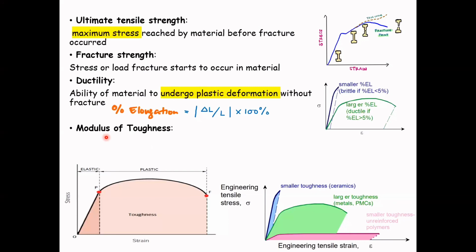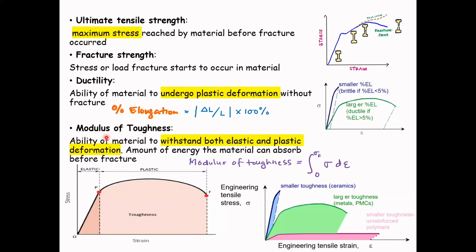It is defined as the amount of strain energy density, or the strain energy per unit volume of material, that a material can absorb before it fractures. So a material's modulus of toughness will vary depending on the material's ductility, and two materials with the same yield strength can vary greatly in their modulus of toughness if one of the materials is more ductile than the other, and the ductile material will stretch further and have a greater area under its stress strain curve.